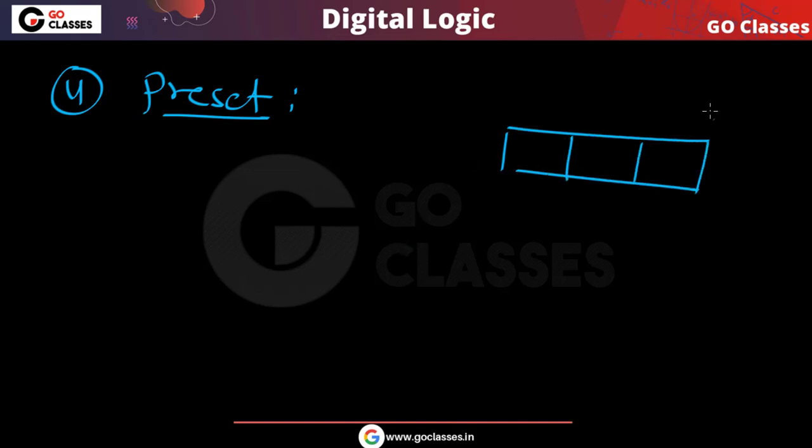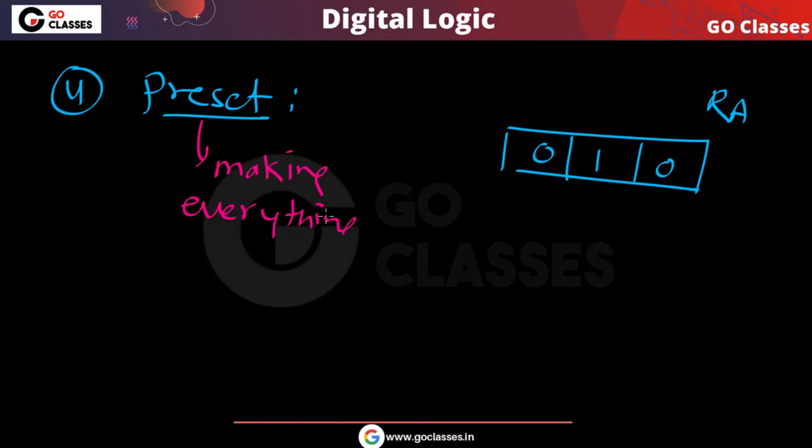Let us assume this is your register, and right now this is your data, and you want to perform some operation on this register. Before you perform that operation, let us assume that you want to make all these bits one. Then you can use this preset input. Basically, preset means making everything one.